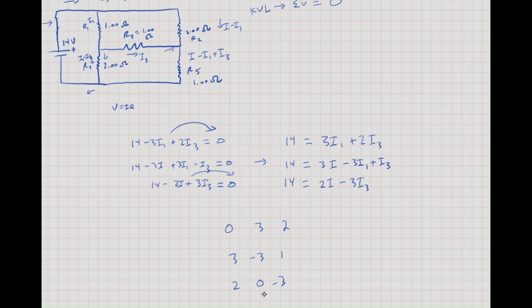But this should be the matrix, and I'm going to make an augmented matrix because this is where we'll get the values of our I's from. And then I'll just go ahead and apply Gauss-Jordan real quick. And this is the answer I got after solving this matrix. So for the total current, we got 10. For the I1, which is here, it's 6. I3, we got 2 amps.